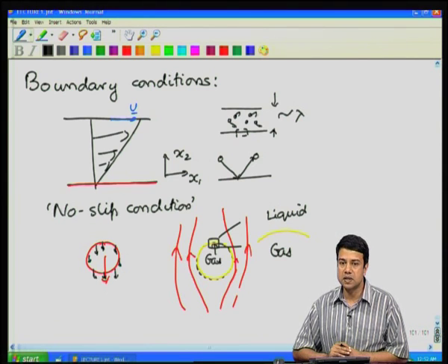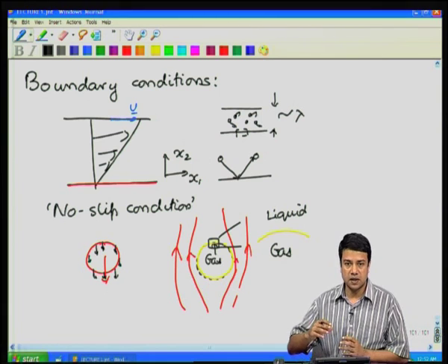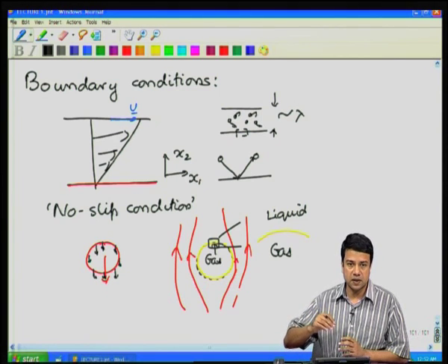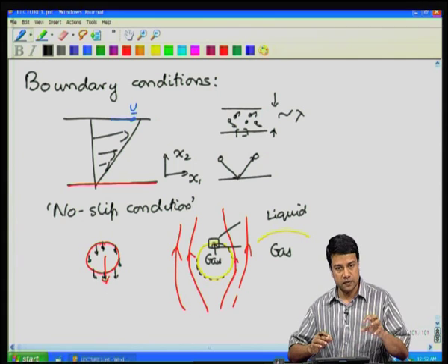Here you cannot enforce continuity of velocity boundary conditions, because the gas itself can move. So, one can have motion in the liquid, motion in the gas, such that at the boundaries the velocity is equal. So, we do not straight away know the velocity in the gas of the bubble as it is moving. For a solid object, of course, the velocity of the surface has to be the same velocity as the object.